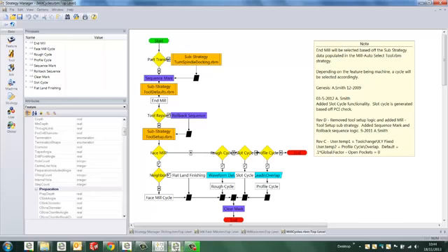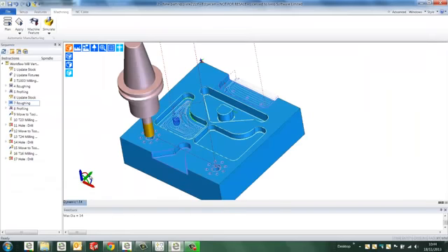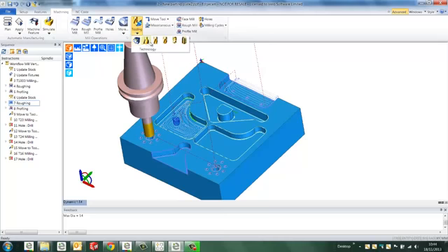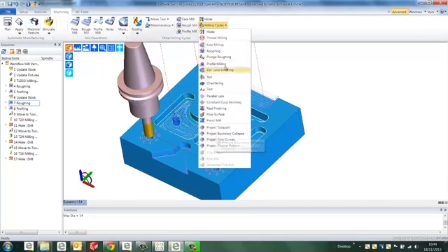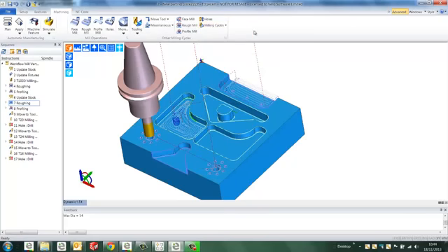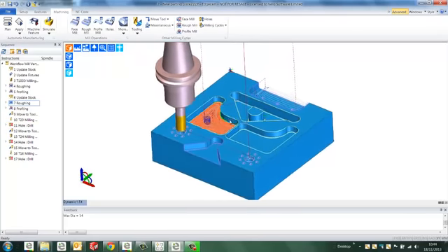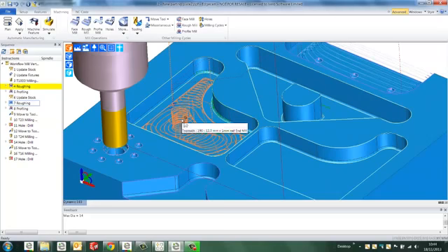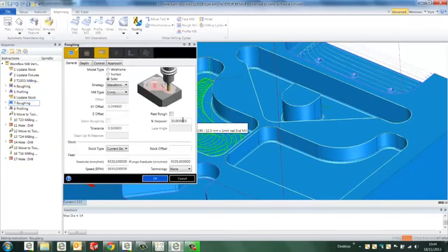Okay, so that was an overview of Strategy Manager. Going back into the workflow environment, just to finish off with, we've focused on automation, but it is fair to say that we can activate the Advanced tab. We can pick tools here, and I could start to apply mill cycles, 5-axis, surface machining. But it's also important to mention that if I'm not happy with the toolpath that's been applied with the automation tools from the Edgecam install, I can actually edit this cycle.